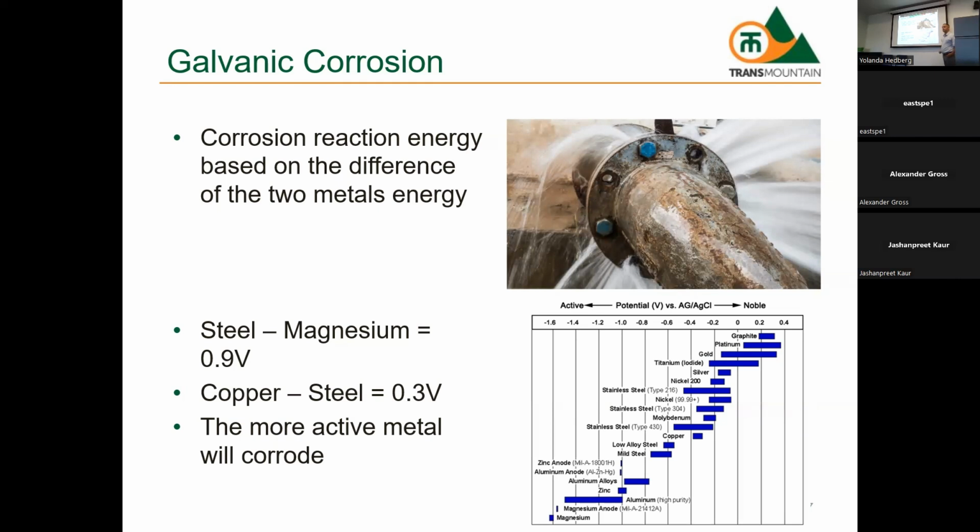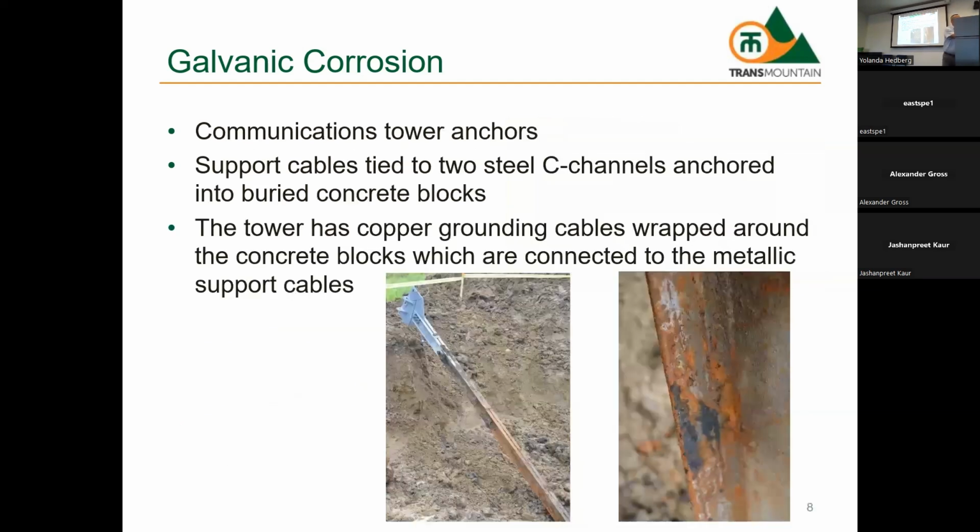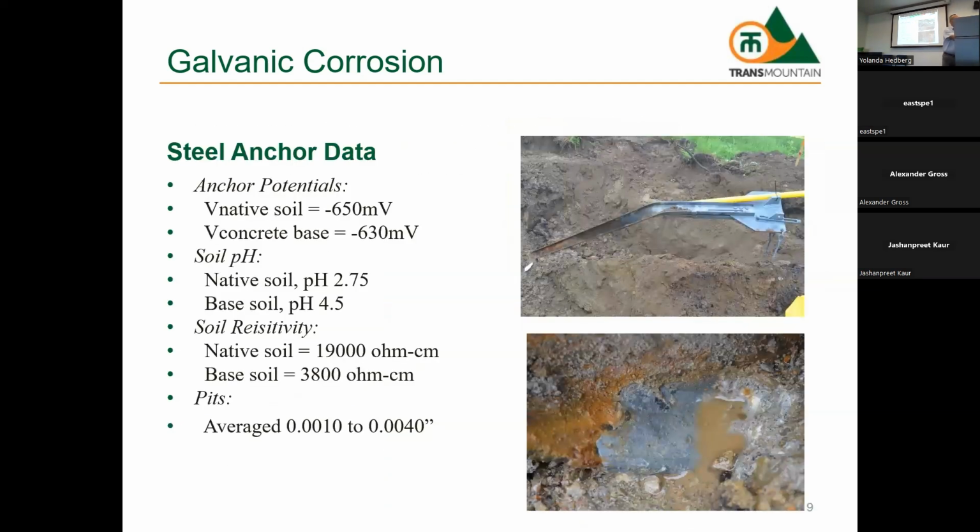And is that done in practice now? Yes. So this one was eye-opening because I'm like, obviously this is the problem. Simple design, just put one magnesium anode in the hole, and it'll protect both the copper and the steel. Very cheap, inexpensive, simple solution. And this company went and put it in at all their sites. Yep. Very simple solution. So how do you have an alarm system when the magnesium anode is consumed?